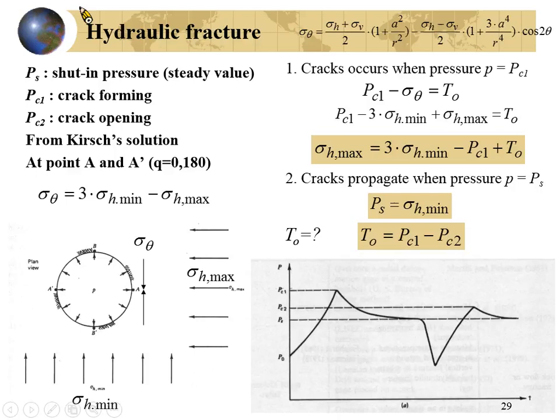But if you have a fracture like this, you will not try to analyze this. And you will directly say, oh, the experiment is failed. Why? If you have a fracture like this, or like low angle, low angle fractures, nearly horizontal, like this, you don't really have any information related to the horizontal stress.